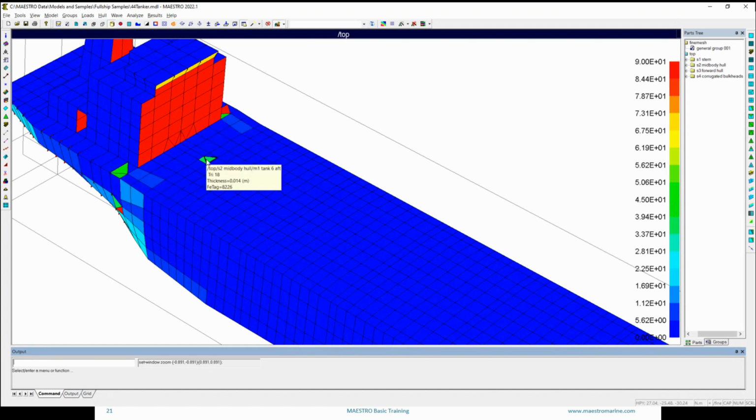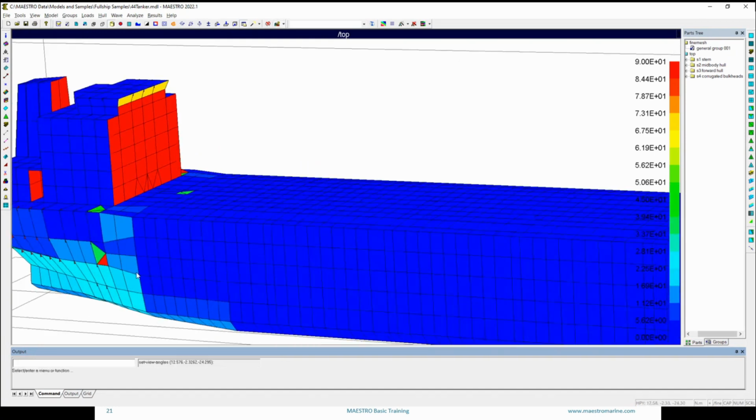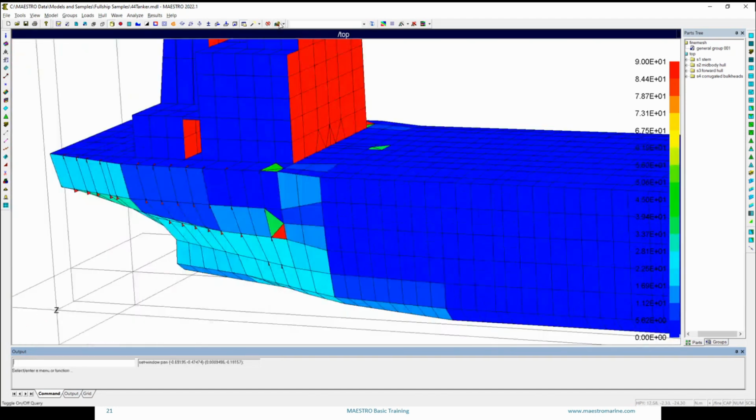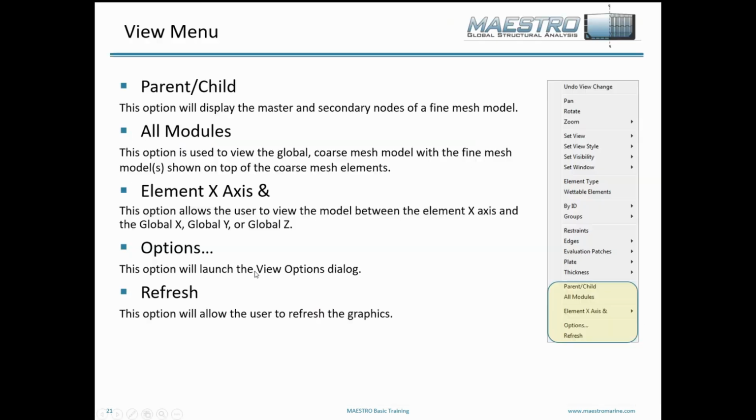If we look at some of these tris, the first edge of this tri, you can see, starts back aft and goes off at about a 45-degree angle. And if we look at the color bar, green is 45. This tri here, and in red, we can see the first edge is going down. So the X direction on that tri is vertical, and again, 90 degrees.